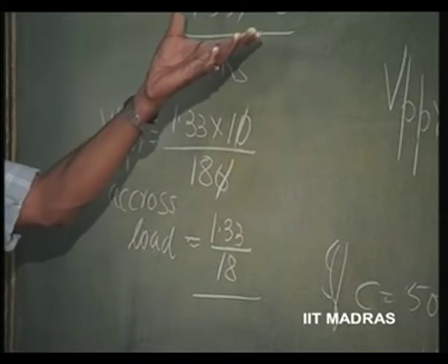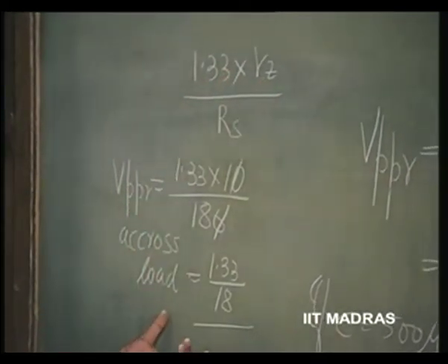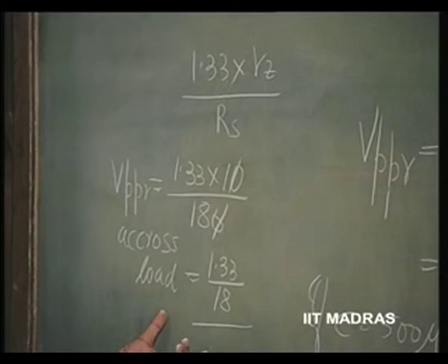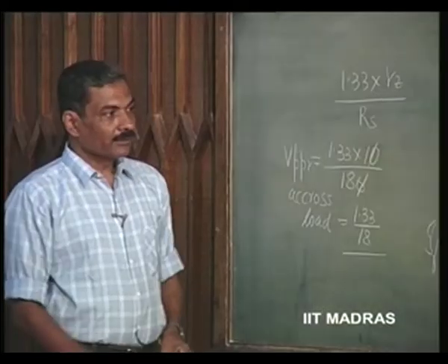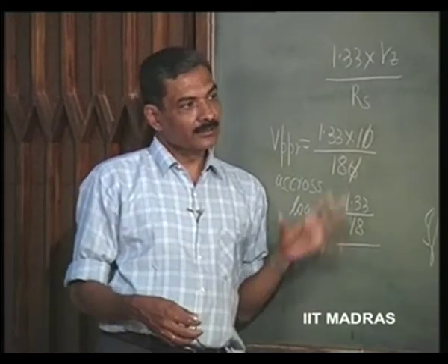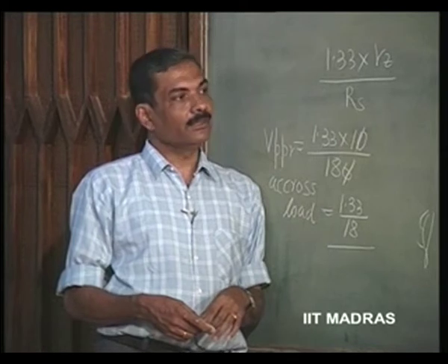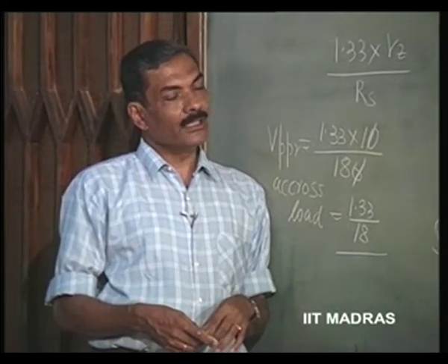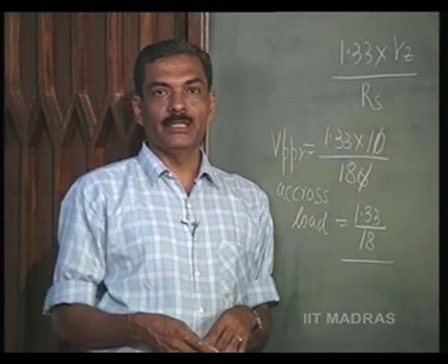You have made use of the small signal equivalent circuit for the Zener in order to evaluate the actual peak to peak ripple that is occurring across the load resistance. So, whether it is design or analysis, you must adopt all these procedures in the case of an AC to DC converter, where the DC voltage is supposed to be regulated.